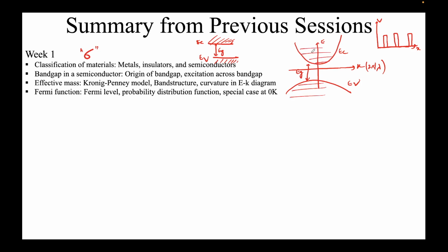These states are so close that they effectively form a continuum, and the curvature that you see of this conduction band and valence band effectively gives you the effective mass for conduction band electrons, and for valence band it gives it for holes. This effective mass is a very powerful entity in the sense that now we can ignore the quantum mechanical effect, so to speak, and wherever the mass comes, we can use Newtonian mechanics. So when we say F equal to ma, force equal to mass into acceleration, their mass m is not the rest mass of electron, 9.1 times 10 to the power minus 31.